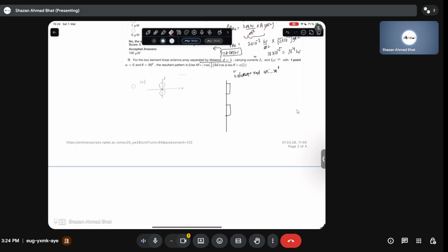Essentially, in the practical scenario, there are something called phased array antennas. I think I've talked about this phased array antenna in week one in a very detailed manner. You can have a lot of these antenna elements that individually emit the electromagnetic wave. Then, based upon the phase differences, these electromagnetic waves can interfere, causing destructive or constructive interference, and it can direct the beam in certain directions. So it's basically a concept of beam directivity based upon the phase differences.